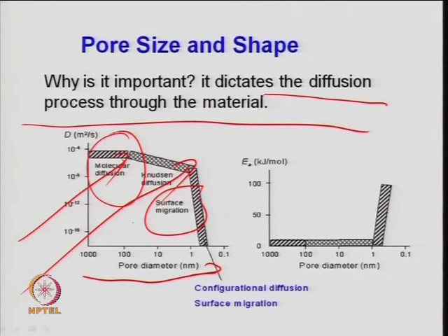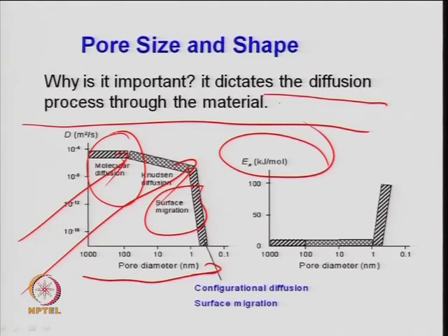So, there are several phenomena: temperature, pressure, everything, and the diameter of the molecule. Knudsen diffusion, bulk diffusion and surface diffusion may happen. That is the first understanding: can a molecule penetrate, and if it penetrates, then how, right, because of diffusion. The convective term may be there, but generally that will be very small because you are talking about the surface of a solid. So, the velocity becomes 0 and then it is diffusing because of the concentration gradient, right. You can see here the activation energy required for these kinds of pores, right. Pore size is increasing on this side, which is why I said that in larger pores you will have molecular diffusion; in the intermediate pores, 1 to 100 nanometer, Knudsen diffusion; and then at very small pores and high temperature, surface diffusion, right.